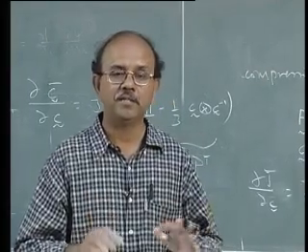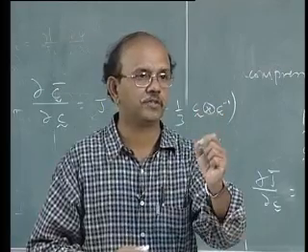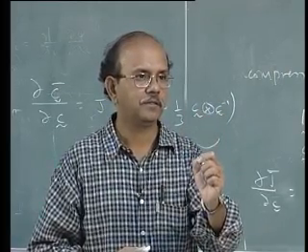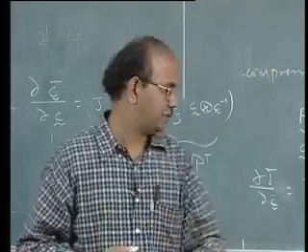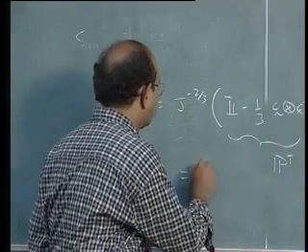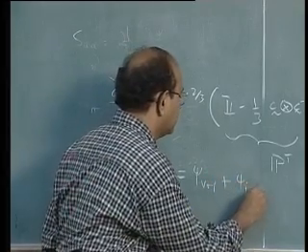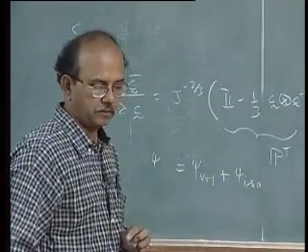So now the theory is very simple. What we are going to do is the total strain energy function is split into two parts. That's all the theory. One is the volumetric part plus the other is the isochoric part.